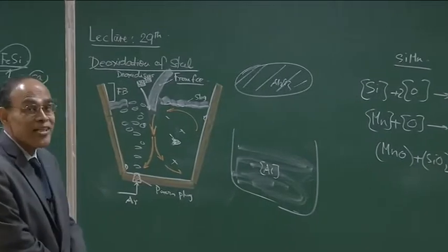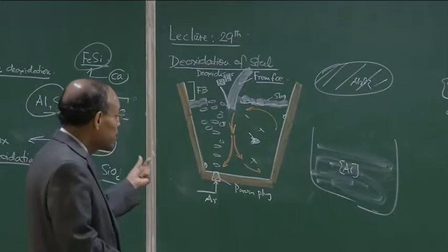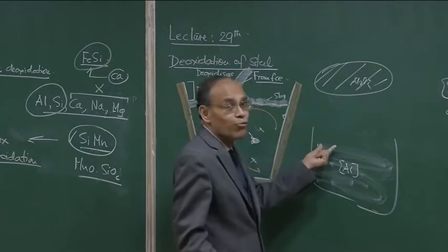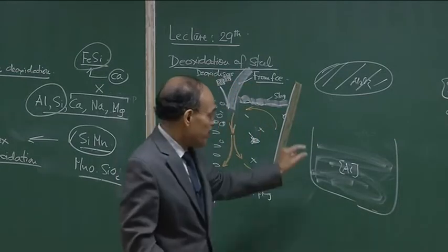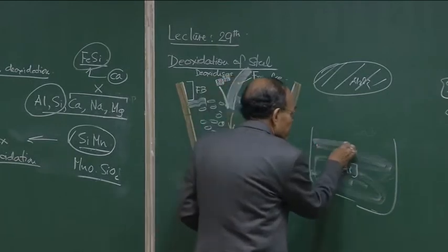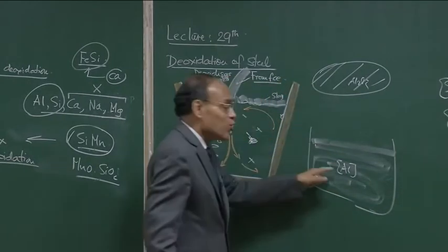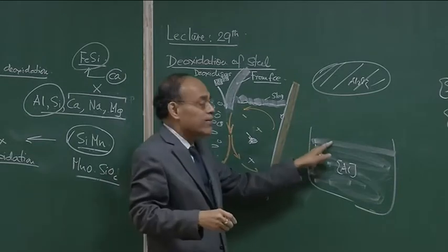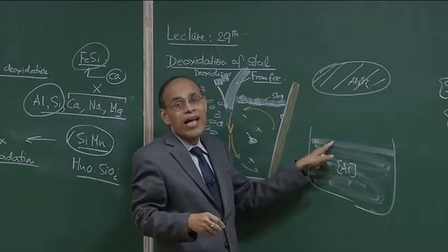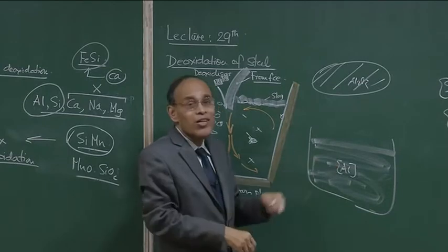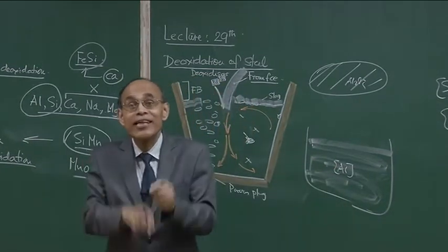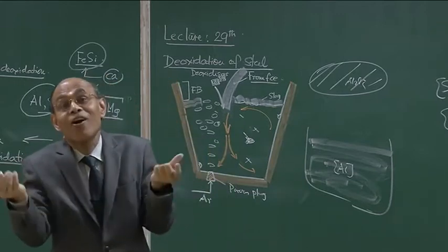And there you must understand, it now becomes clear that this calculation is going to be totally disturbed if you have FeO present in the slag phase. The aluminum, because it is lighter, floats up after you add it, and gets exposed to a slag which contains iron oxide. As a result, rather than going into the melt and reacting with it, the aluminum reacts with FeO, which is unaccounted for.